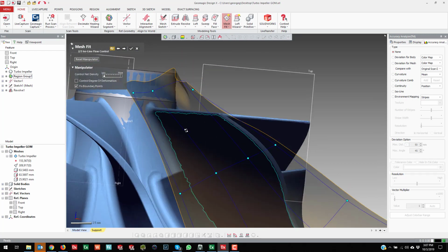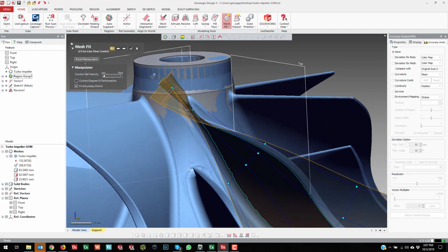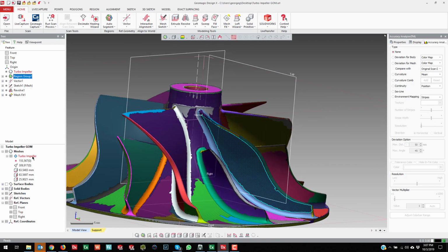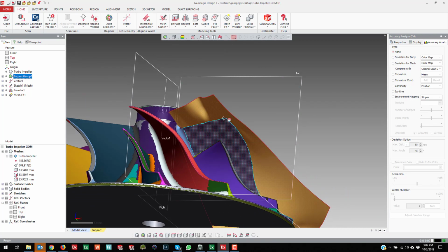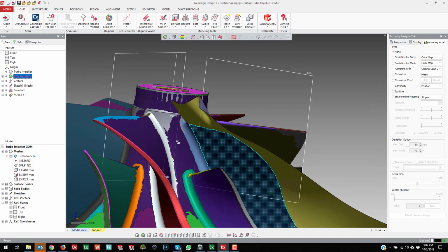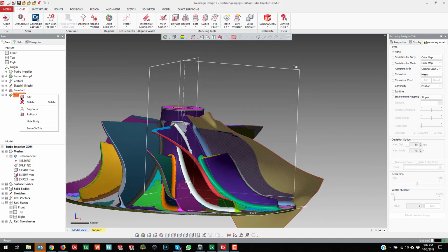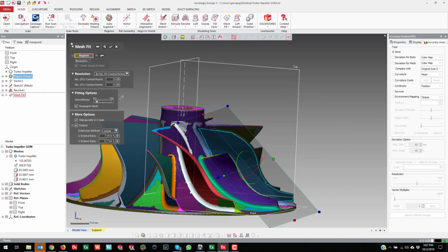And it's a little bit wrinkly there, so let's just take a look at it here and see what we end up with. It's a little more wrinkly than I wanted, but you're not stuck with it. You can come in here and adjust the settings, so I can apply a little more smooth, and I can even lower this down resolution wise. I could say 20 by 20.